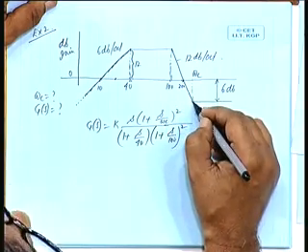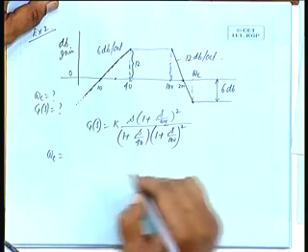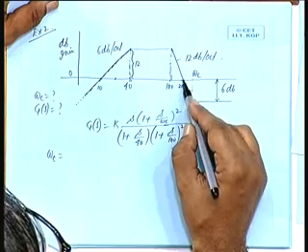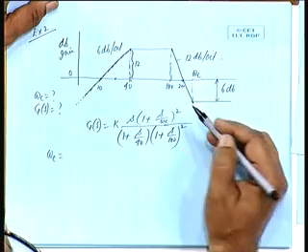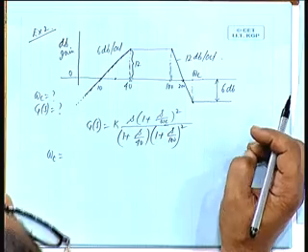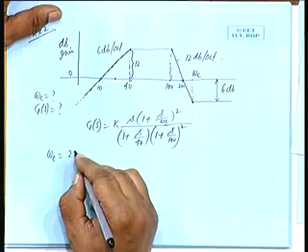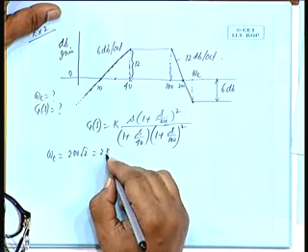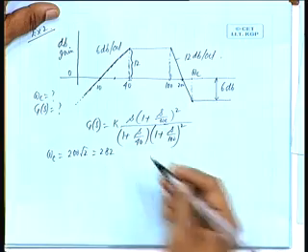So, how much is omega c? 200, instead of going to 400, it is not an arithmetic mean, root 2. Instead of 2, it will be 2 to the power half, it is a power. So, omega c is 200 root 2, all right, 282 approximately, is it all right? So, substitute that omega c, you get the form.